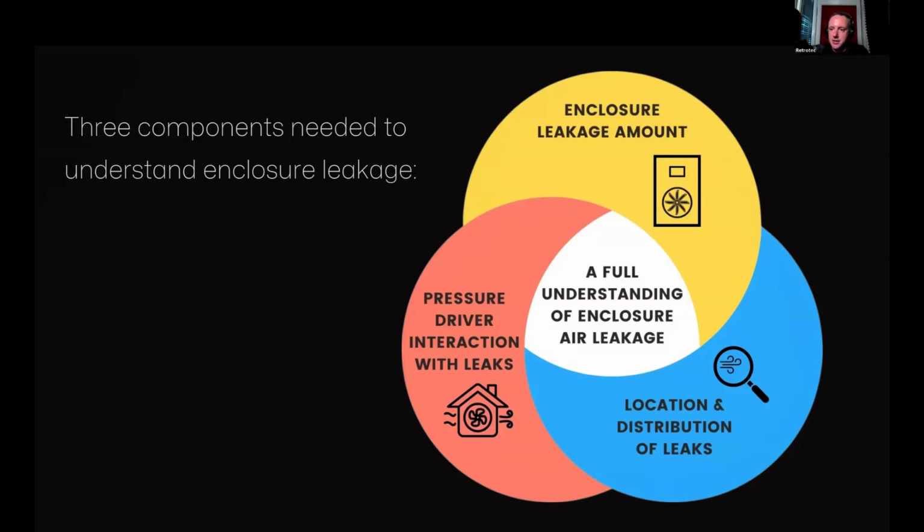If we start shutting interior doors that don't have return air pathways, then those rooms get either pressurized or depressurized, and then cause certain parts of the house to leak harder or leak differently than other parts. And so we can use high resolution manometers with the mechanical systems running to really investigate that. That whole process is called MAD air.